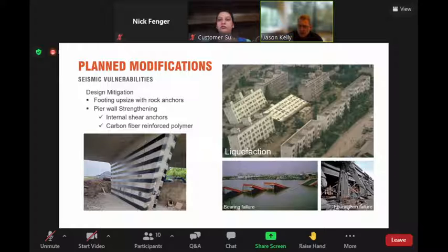So when we looked at this bridge, the geotech came out and looked at the soils around there, and they weren't really concerned about liquefaction. There's good bedrock, basalt, lava rock, pretty shallow under it. They looked at bearing failure, and based on the bridge being two-span continuous and cast into that center pier, and the end piers having plenty of room for the beam to sit, they weren't really worried about bearing failure at all.